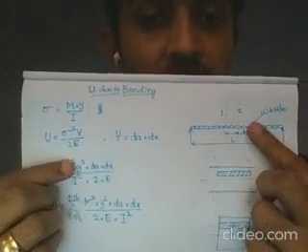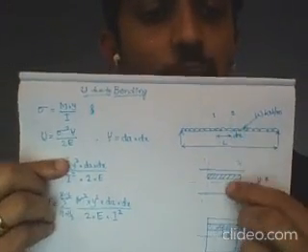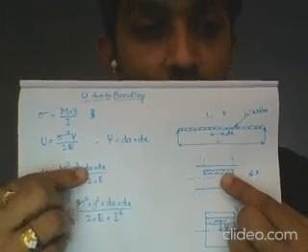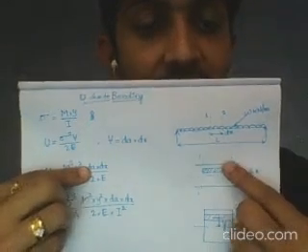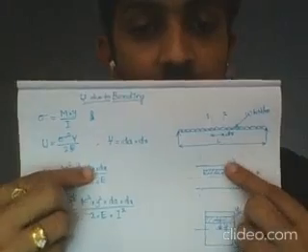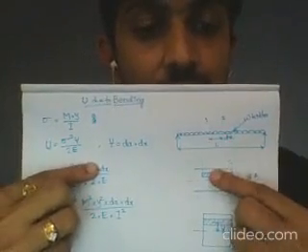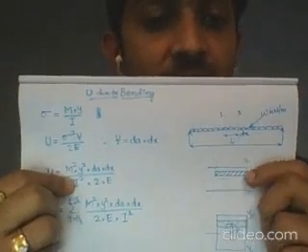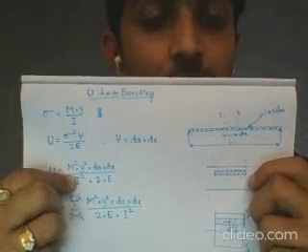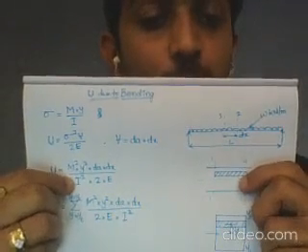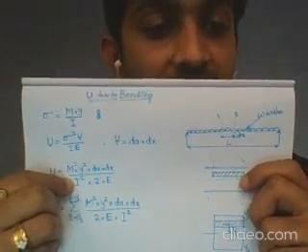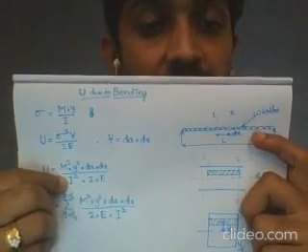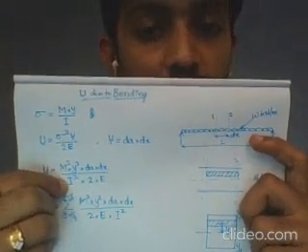So the moment is constant, and the distance y depends on the location where I am considering the element. dA is the cross-sectional area, which depends on the thickness and the width, the other dimension, and dx is nothing but the length. Young's modulus is again constant, and for the moment of inertia, I am considering a rectangular element, so I need to deduce the moment of inertia of that element. If the beam cross-section is also a rectangle, then the moment of inertia will be easier to deduce.